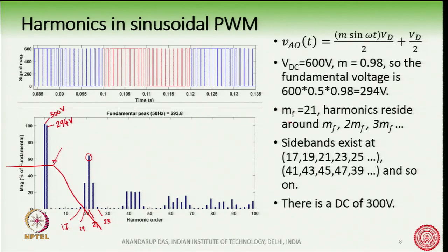If we choose the corner frequency in a clever way, then we can make the gain plot in such a way that for all the harmonics here, the gain is 0 or less than 0 at the harmonic frequency and all the higher harmonic frequencies. Therefore, the filter will get rid of all the harmonics present.